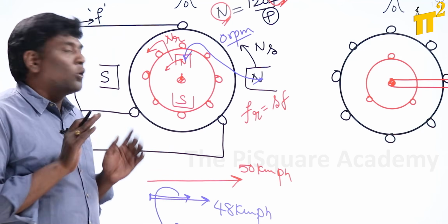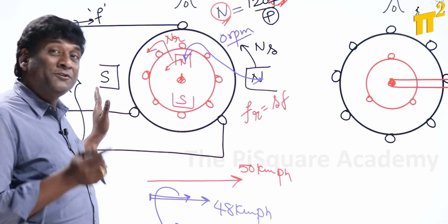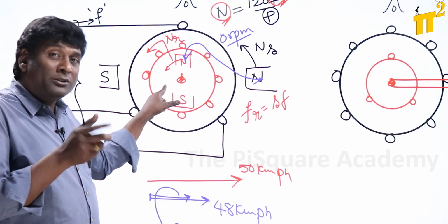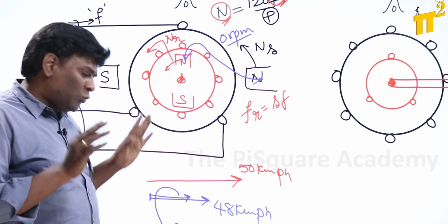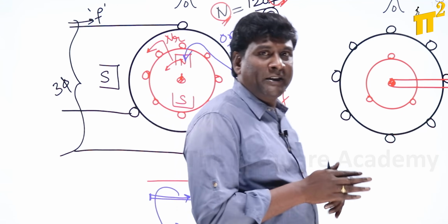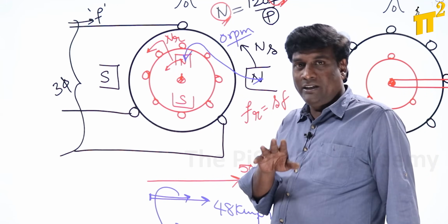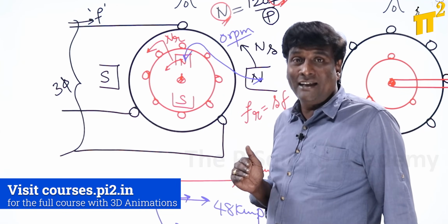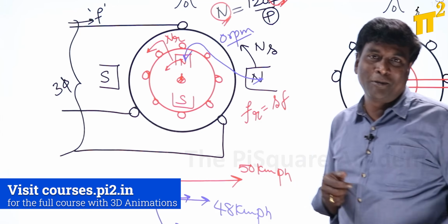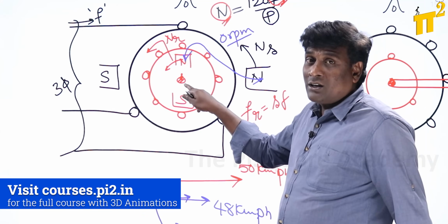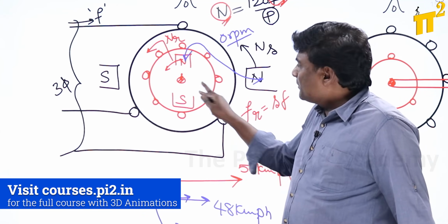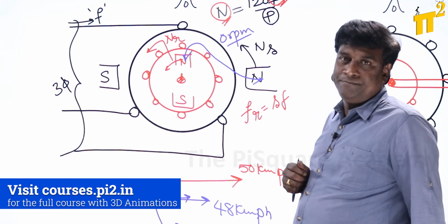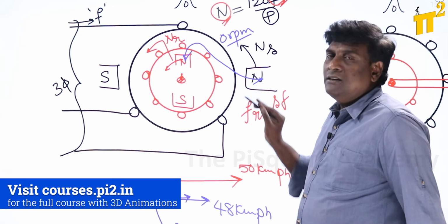Now, what conclusions have we taken here? The stator is provided with a fixed frequency supply, that's why stator MMF will not change. And the rotor, depending upon the load requirement, its speed should always be less than synchronous speed. But how much less than synchronous speed will be decided by the load. My rotor may rotate at 2900 RPM, or at 2500 RPM, or at 2700 RPM. Getting my point, right? So that is one conclusion.